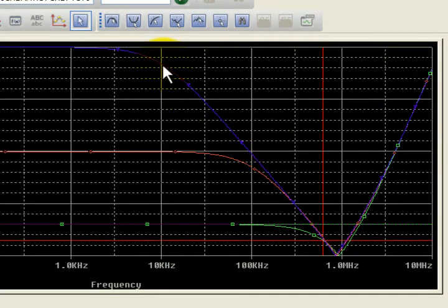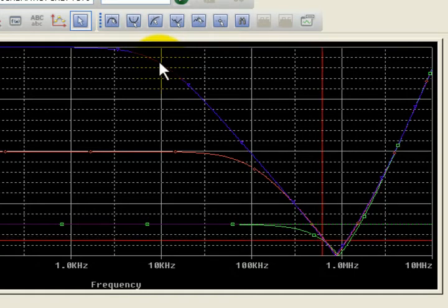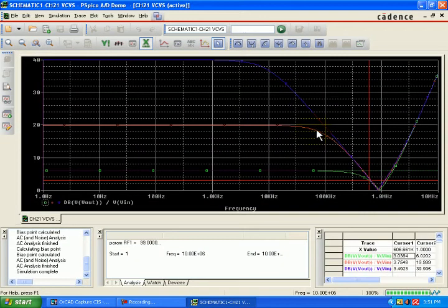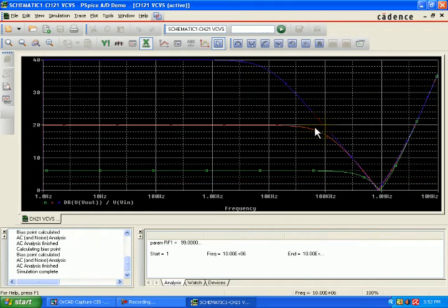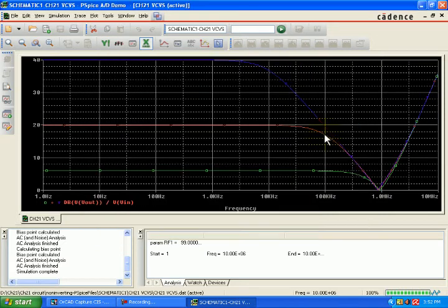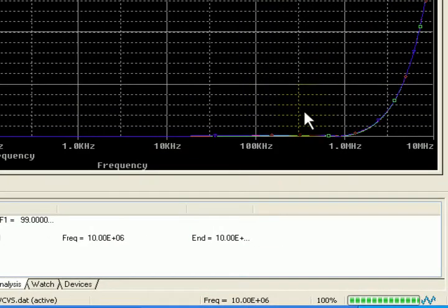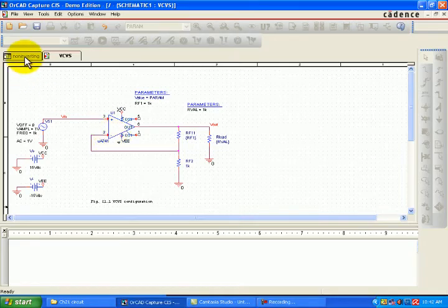This is the analysis of the signal to noise ratio for the different values of RF1. If we increase the value of the feedback resistance, there are changes in the SNR. For all the curves, the ideal formula of midband gain approximately holds, and also the new values are 378.8, 196.